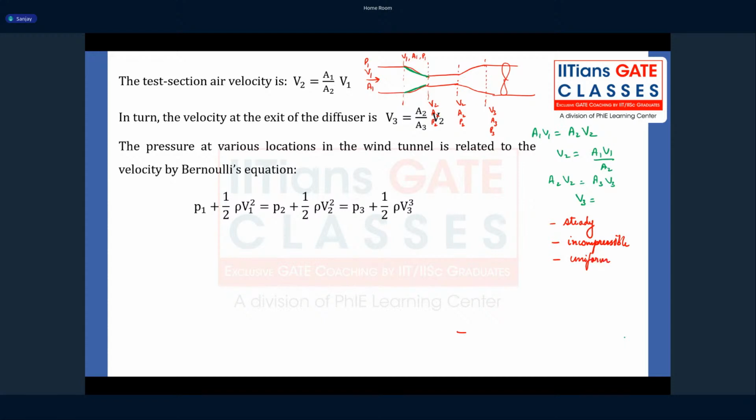If the flow is not uniform, or I mentioned the quasi 1D assumption. Okay, it's a quasi 1D flow. If the flow is not quasi 1D, then again the way you apply mass conservation is not the same. Okay, and you also assume that there are no body forces. So you are neglecting the gravity.